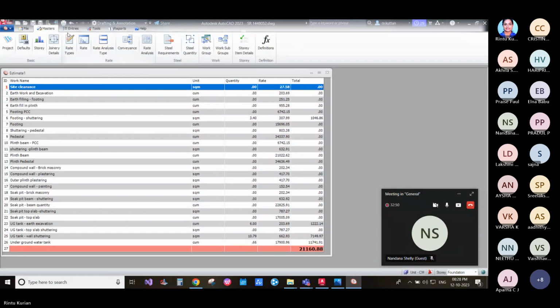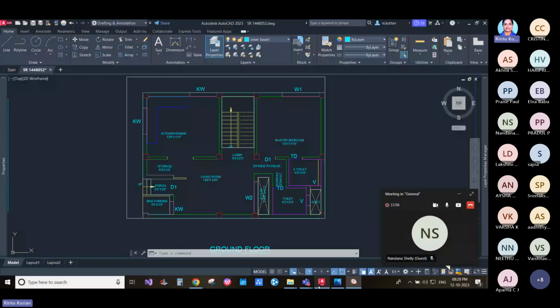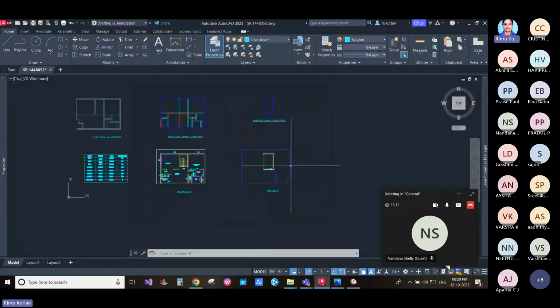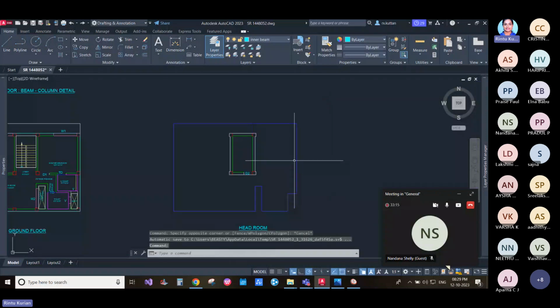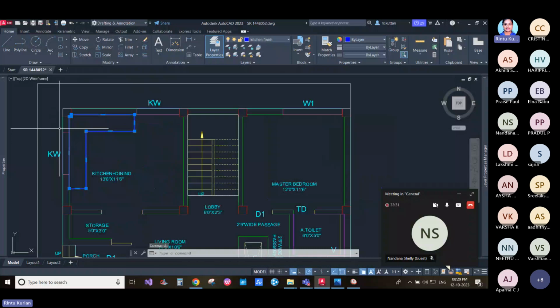That means these entities like the kitchen slab or the reduction for this particular area or even the terrace waterproofing. These are entities we cannot define as such. This will vary with each project. So in order to cover such entities, such calculations or quantities which vary with each project, we are using certain polylines. These polylines are called CAD utilities. So the kitchen finish is denoted by a polyline having a layer named kitchen finish, and this is scanned into the Estimax to get the area to be covered with granite.